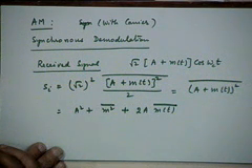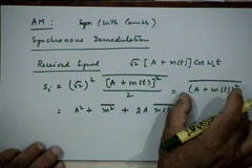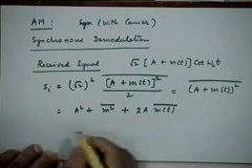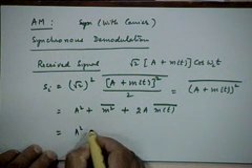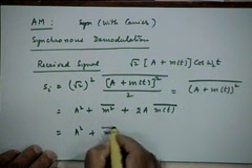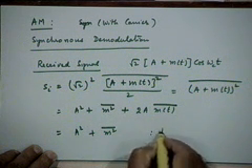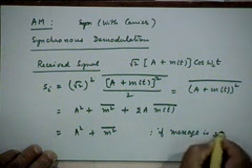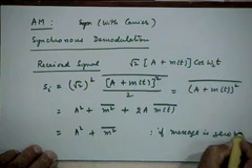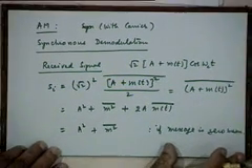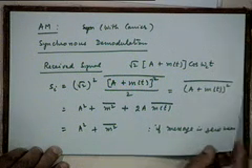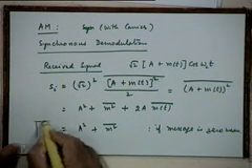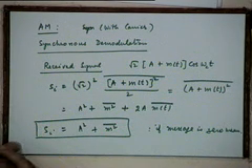I just expanded that, and if you assume that the message is 0 mean, it is A squared plus m squared bar. This means the message has no DC component. Okay, so this is your expression for the input power.